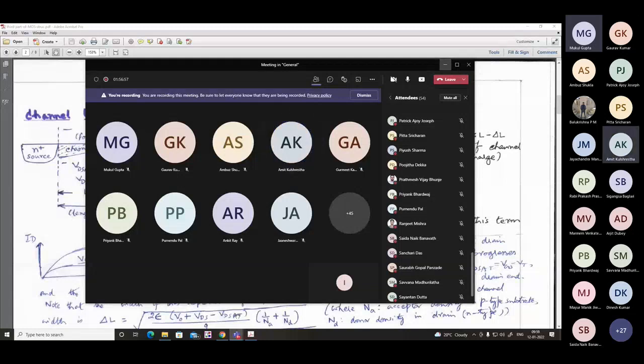In the beginning of the course, we are studying some device aspects. Later on, we shall move over to scaling, as we are in the deep submicron era. Next we'll study the short channel effect and the narrow channel effect. Then we'll move on to MOSFET capacitance, and having equipped our knowledge with these concepts, we'll move on to the design of inverter, and then combinational gates and all that. We are only glancing through the device physics, but mostly our concentration will lie in the design aspect.